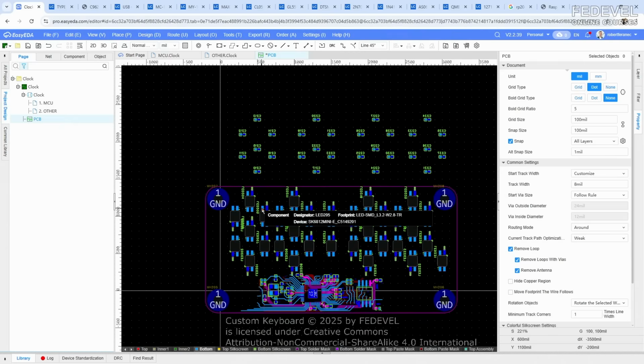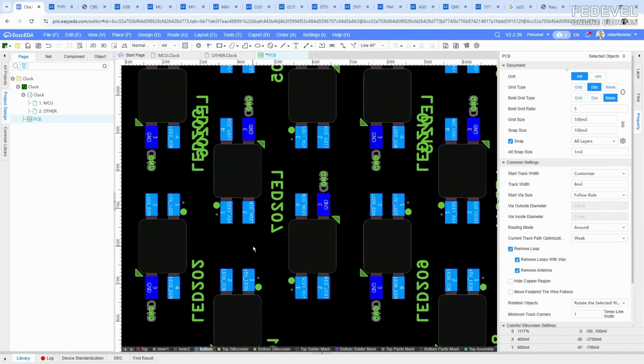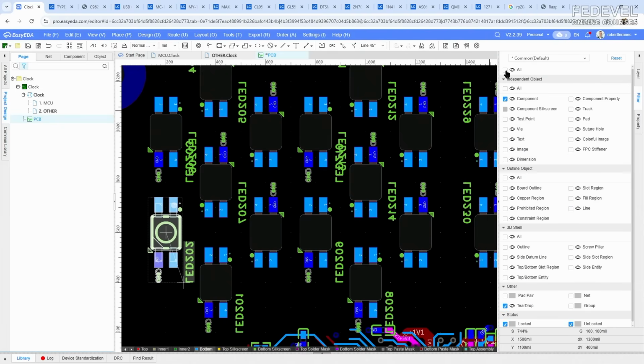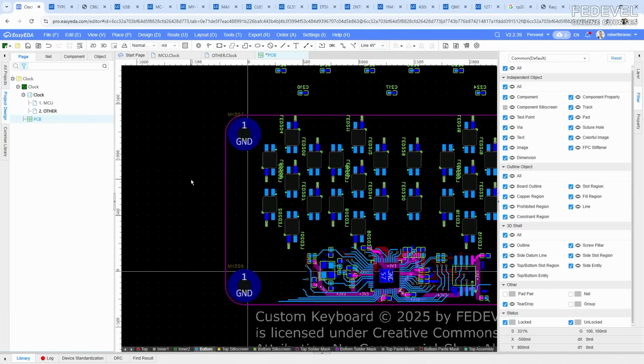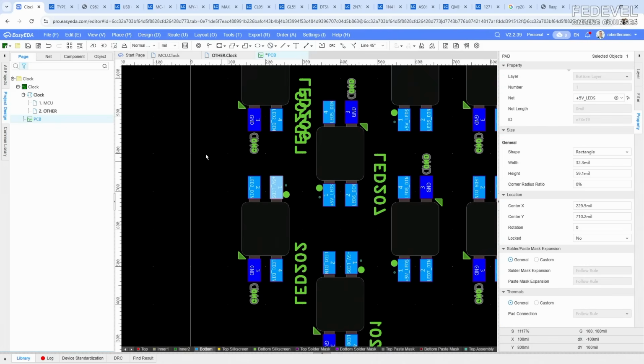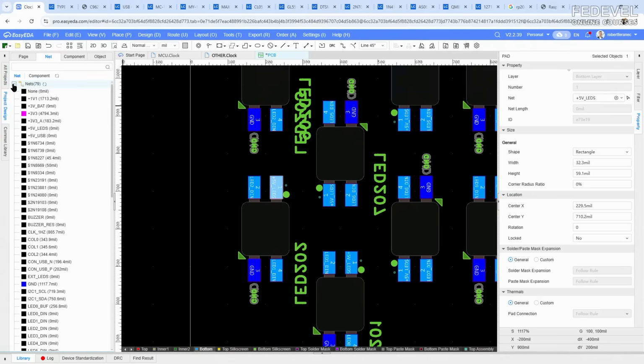Okay, zoom in and watch where we would like to place it. We need to place them close to the power pins. So what I'm going to do, I'm going to find the power here and I'm going to change the color. We can use orange.